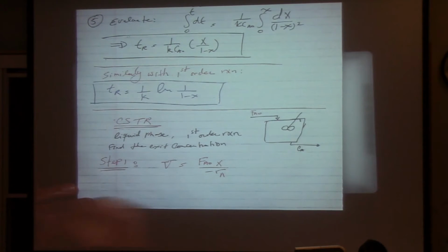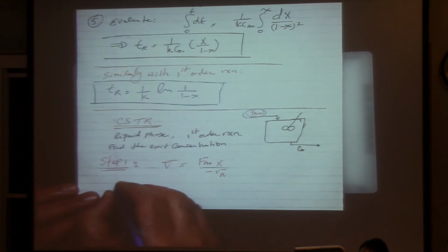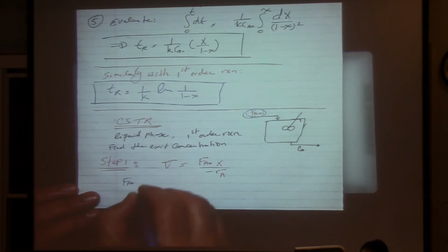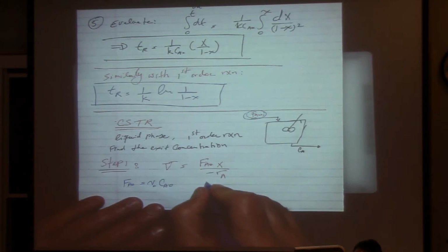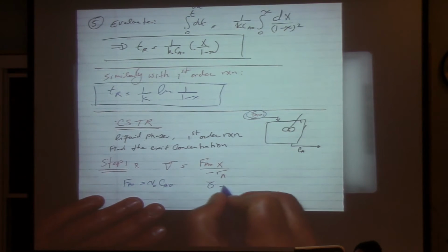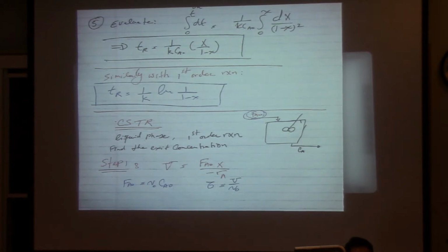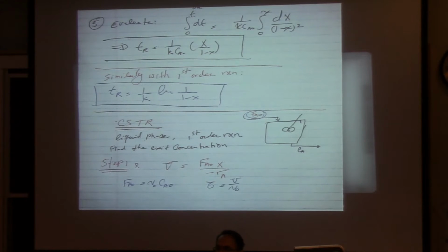Since we are dealing with the molar flow rate, just get your attention to this equation. We have FA0 is V0 CA0, and then, if you remember, we discussed tau, the space-time, which was V, capital V, over V0. So you can convert this equation to include tau rather than X. The reason is that sometimes you have tau as a design equation, like they might give you the tau, so you need to convert the equation in terms of tau. Nothing fancy, we don't do anything extra here.